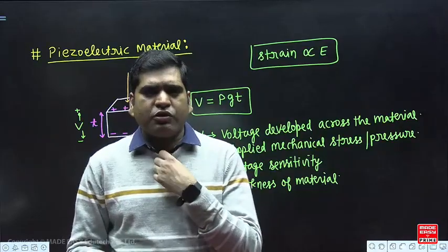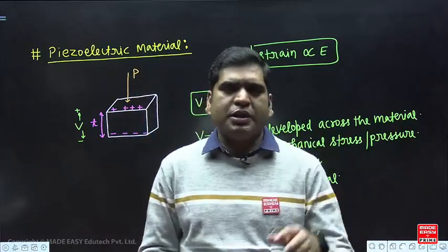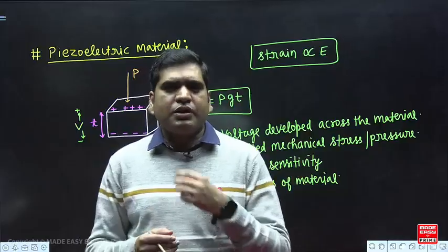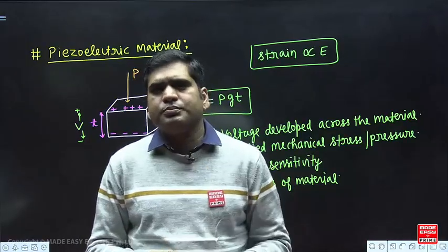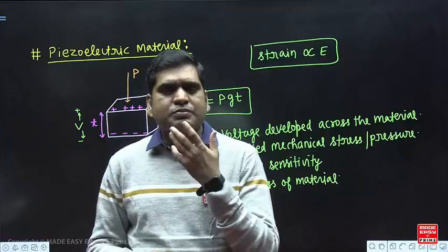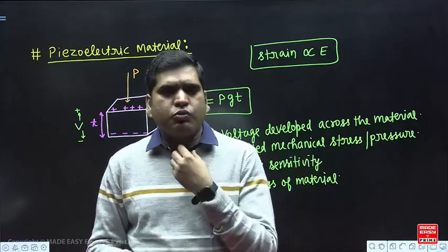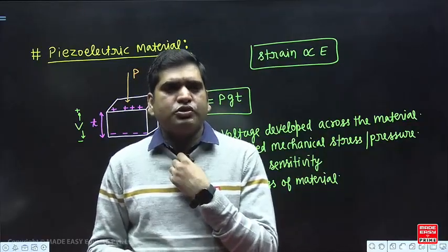Let us suppose this is the microphone through which my voice is getting amplified to you. So in this microphone there is a crystal, piezoelectric crystal. So when I speak, some sound waves are coming and these sound waves put pressure on the piezoelectric crystal.